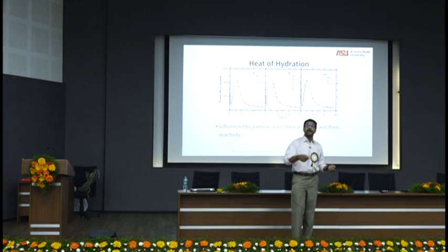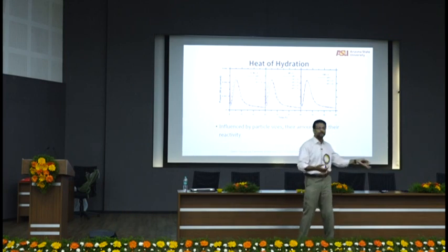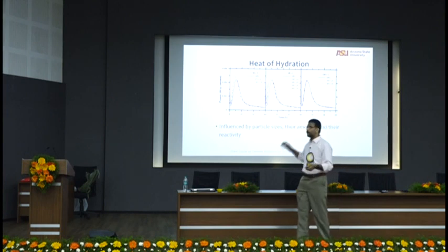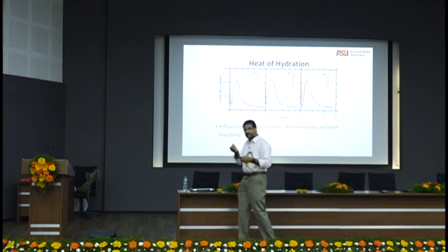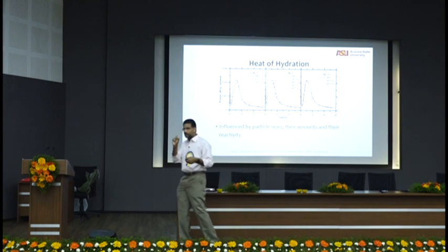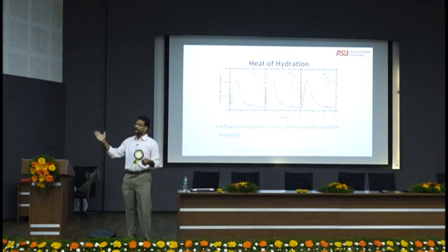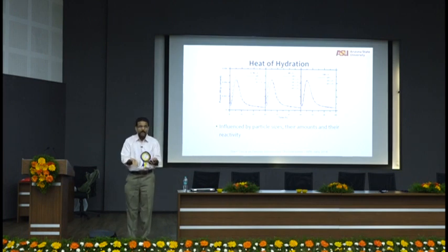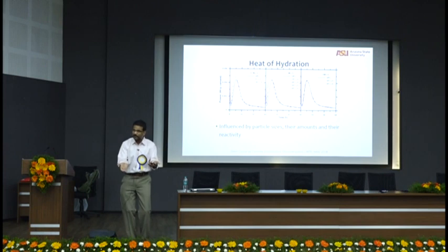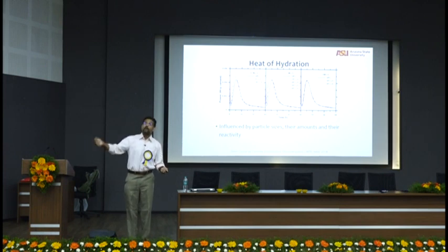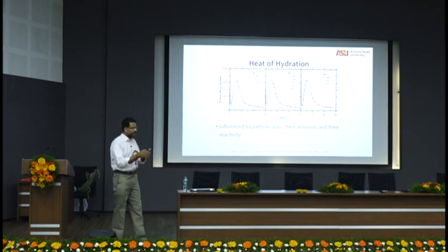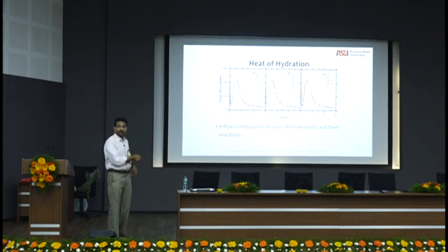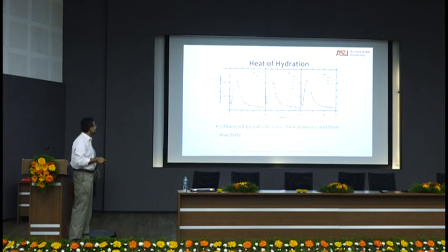So it is called heterogeneous nucleation. It needs a surface to precipitate on, and therefore, when you have a cement grain or a fine limestone particle as a surface, calcium hydroxide starts to precipitate on the surface. When it precipitates, the solution becomes undersaturated in calcium hydroxide, so more reaction will happen from the cement, more calcium hydroxide and CSH will form, and therefore your heat will be more.